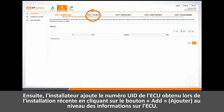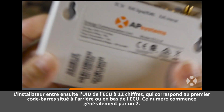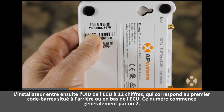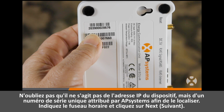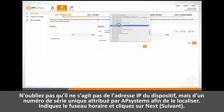Next, the installer adds the ECU UID number from the recent installation by clicking the Add button on the ECU Info step. The installer then enters the 12-digit ECU UID, which is the topmost barcode located on the back or bottom of the ECU, typically beginning with a 2. Take care when entering this number, as an incorrect ECU number entry will not enable communication with the site. Keep in mind that this is not the device IP address, but a unique serial number assigned by AP Systems to locate the device. Enter the time zone and click Next.